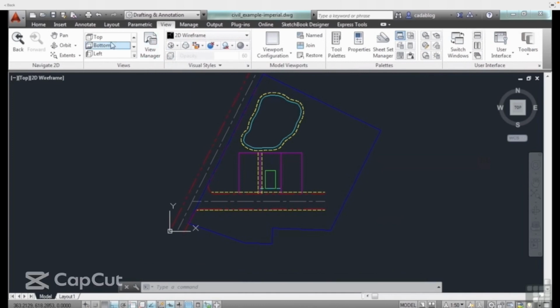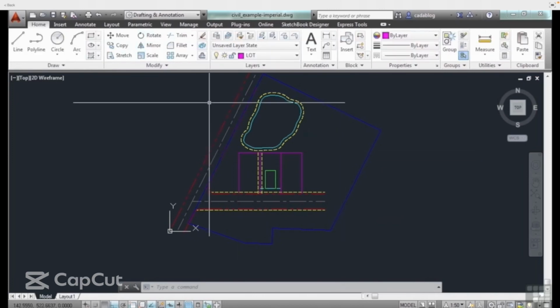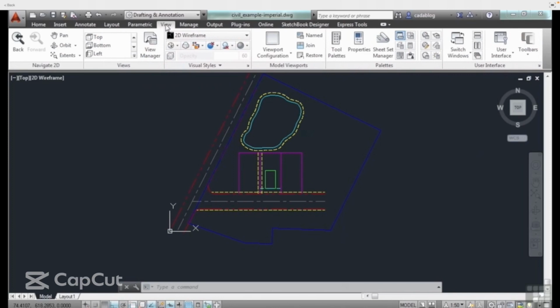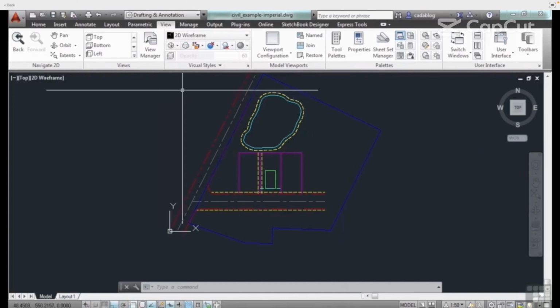And here you have different preset views, top, bottom, left, right. These are all for the different 3D views. You can go to the View Manager to help create or make some. Or you can go up to the ribbon. Go to the View tab, and you need the coordinate panel. Now by default, this coordinate panel doesn't show up. I'm not sure why it's set that way, but out of the box, that's what's happening.